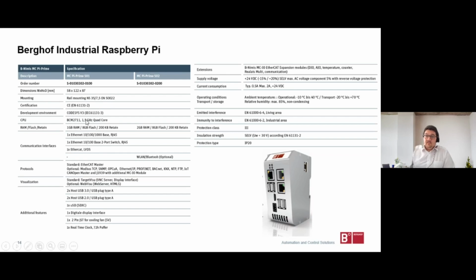we have the Codesys runtime, the quad core, the same amount of memory, but additionally to the gigabit Ethernet connection, we have a second Ethernet connection here with two ports. That is a switch, and we also again have the native EtherCAT. The protocols that are supported are the same. The visualization that is supported is also the same.